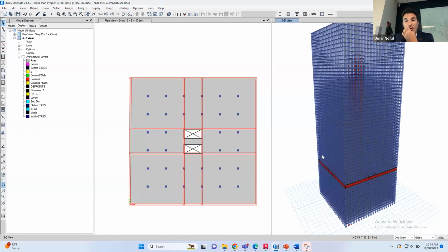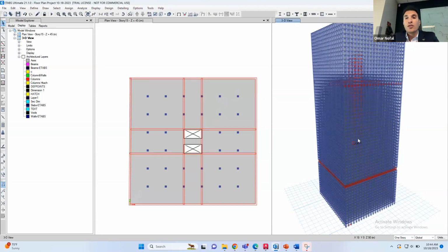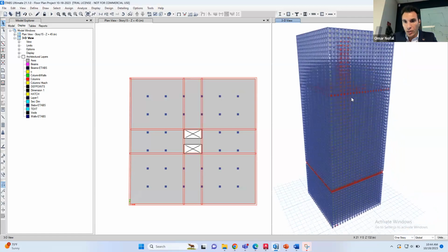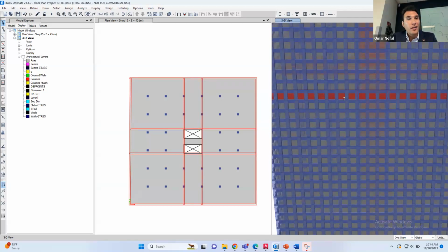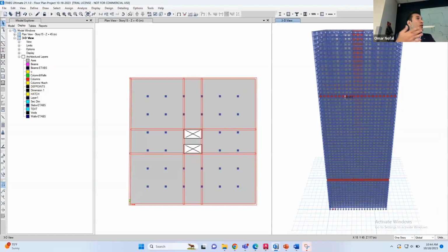So once you do this, make sure that you don't have overlapping sections, wall inside a wall. So right now you got all the outrigger. Yeah, but can you see here? What we have here is columns inside walls, okay? So you need to delete the columns, delete the wall sections so you don't have an overlap, but this will help you to save you some time redrawing again, okay?